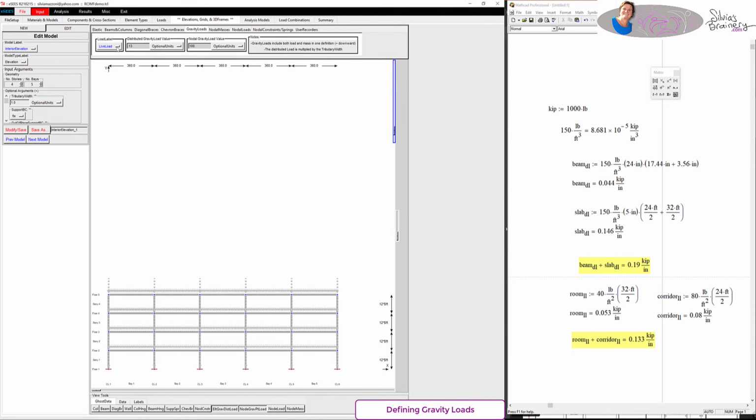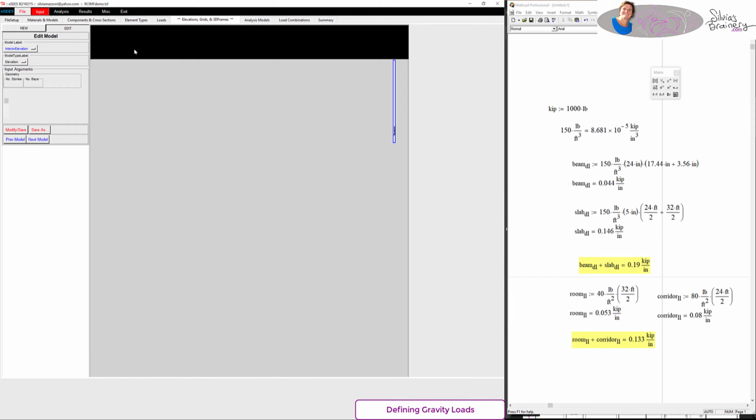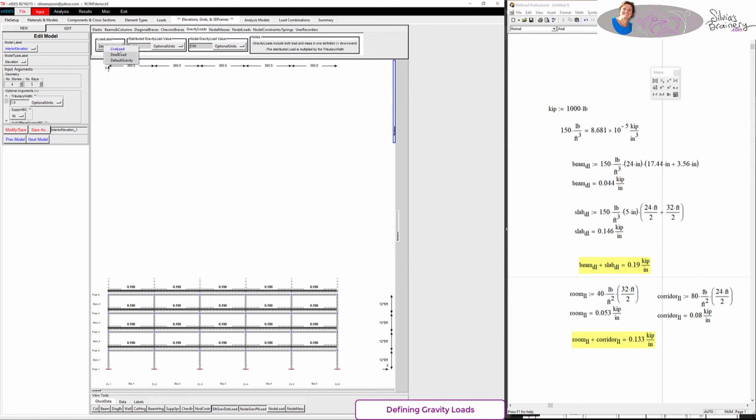Now what you want to do is go to gravity loads. And remember, gravity loads are going to be downwards, okay? Downward is, quote unquote, the positive direction. So I will go in and put a negative into OpenSees. So now I've defined the dead load, and remember to assign that tributary of 1. And then, because it's the same for all the floors, and I think that could be different and that wasn't documented in the report, you assign that live load to all of them.